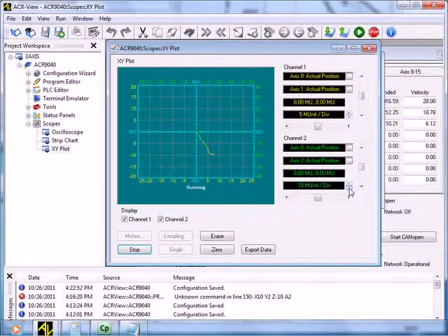With the tangential moves, what it does is if there's a point on the x and y axis, then it's going to add another move in between the two moves of the path, so it orients the z-axis rather than commanding an instantaneous jerk on that z-axis, which would be liable to trip that out onto a tracking error. Would also be very hard on your mechanics if you were machining parts. So it does have the look ahead feature on there.